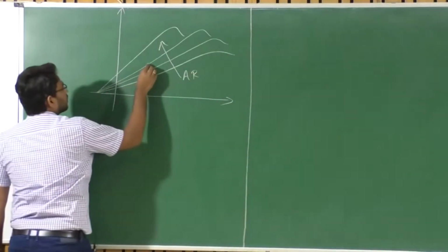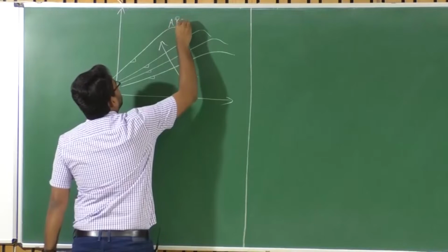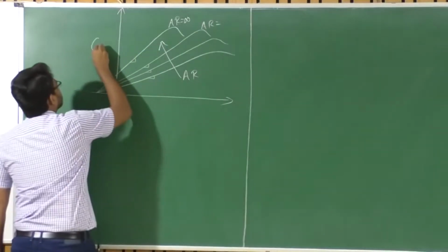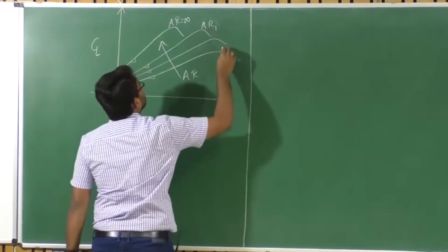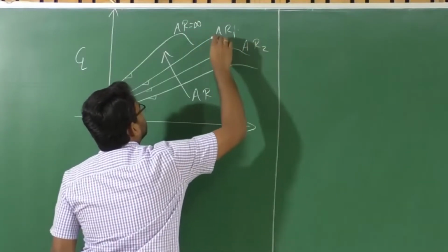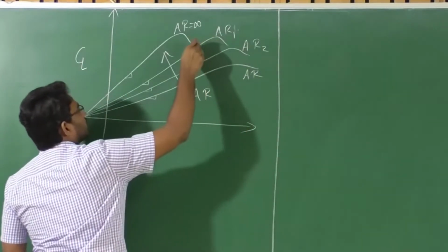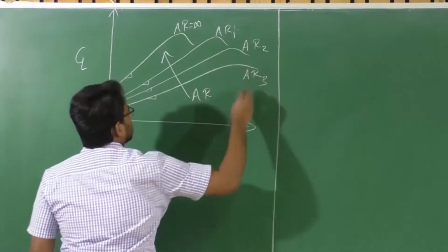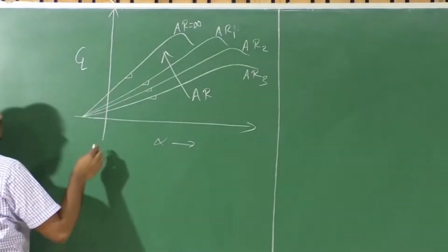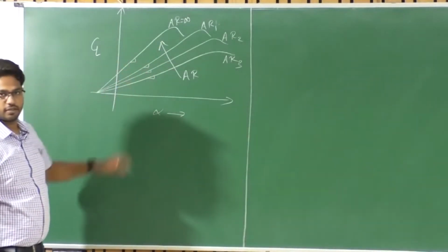So the CL alpha decreases, right? The lift curve slope decreases. So this is for a wing of infinite aspect ratio or for an airfoil. So this lift curve slope represents a lesser aspect ratio compared to that of an aerofoil. So this is where the finite wing starts, right? From this plot we are talking about finite wings. So this is the variation of CL with angle of attack, right? So if we observe, as the aspect ratio increases, CL alpha increases here, right?